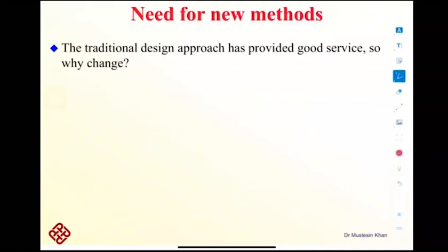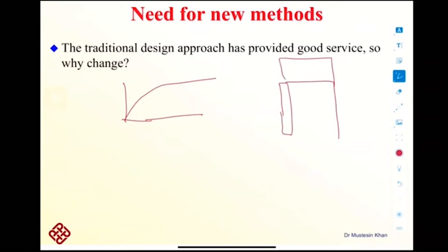Because you already know that there are so many disadvantages associated with this, such as the nature of the fire exposure, the time-temperature curve, which gives you always increasing temperature, and the interaction of the column or the beam with the rest of the building. You are missing it, the interaction of that tested component with the rest of the building.